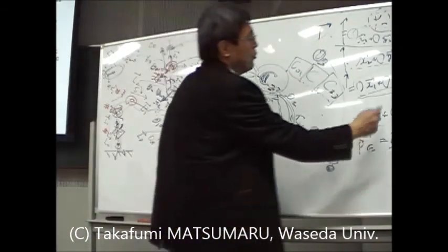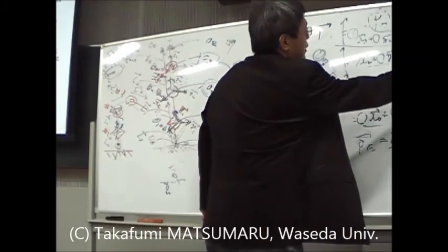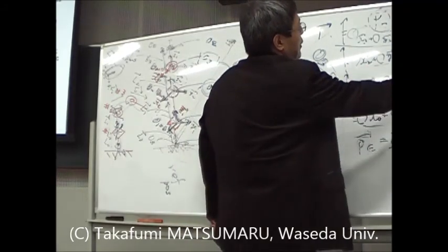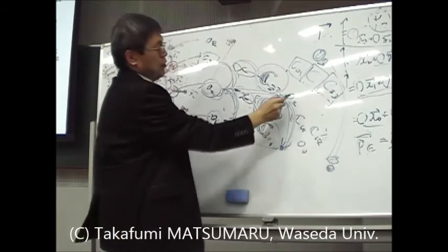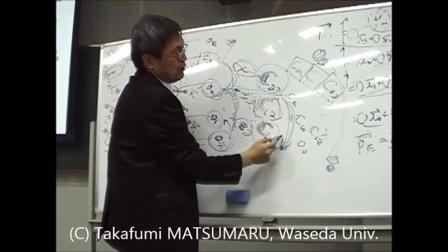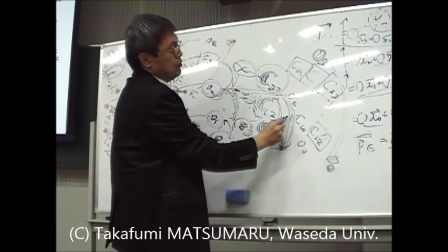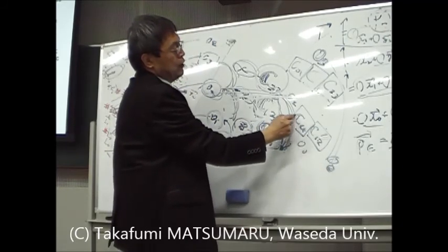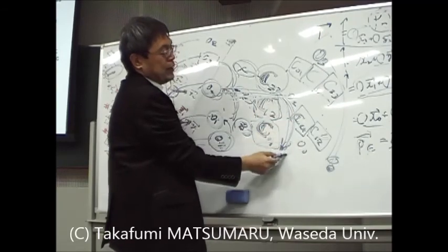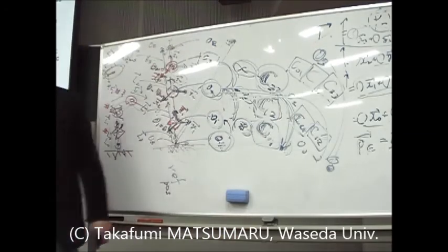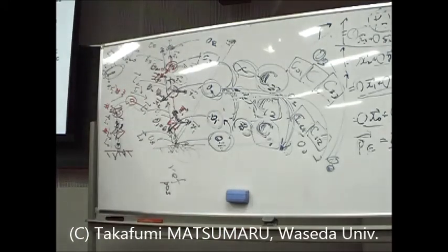Also this second link vector is expressed in the second local coordinate system. From the second local coordinate system to the basement coordinate system, C12 and C01, these two 3x3 matrix transformations are necessary to translate into the basement coordinate expression. Okay, only that.